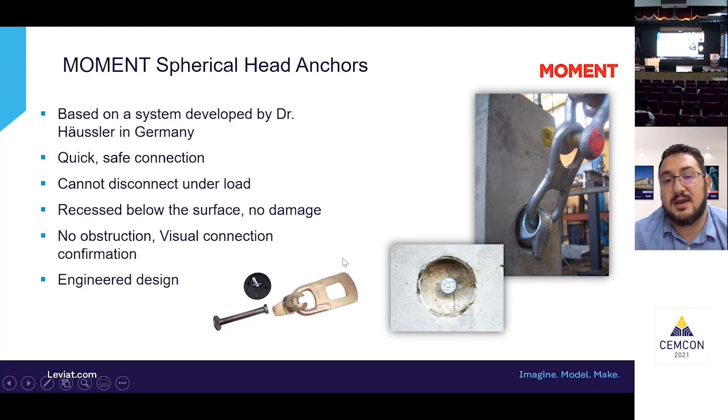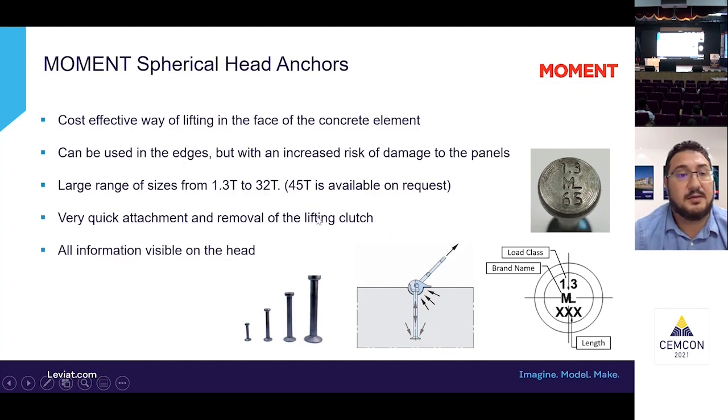They are installed using recess formers, so that the anchors are situated below the surface, so they can't be damaged during transportation or stacking or storage. And it also allows a quick finish. You can simply fill the little recess with grout and provide a flush finish with minimal rework of the unit. Most importantly, they are engineered design. The capacities are calculated based on international standards, which I'll give a quick overview of later in this presentation.